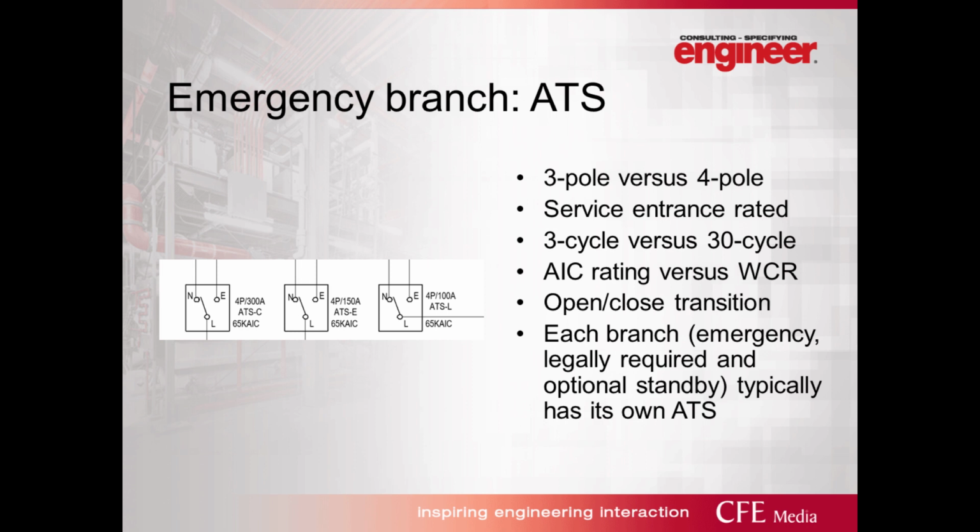The UL 1066 rated upstream breakers are required for 30-cycle ATS. Most branch breakers in low voltage systems are UL 489 listed. For these breakers, 3-cycle ATS is sufficient. Similarly to the switchgear, a 30-cycle ATS makes it easier to coordinate the system to assure power reliability.